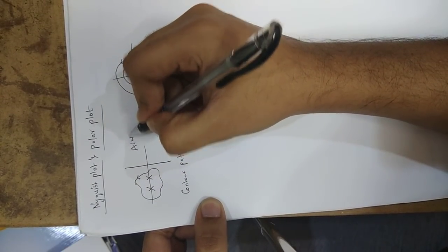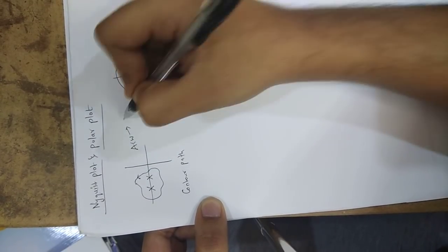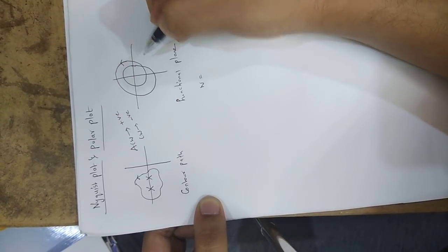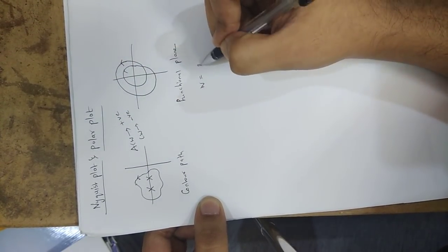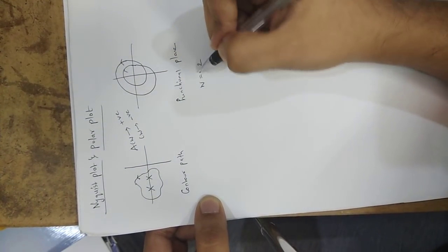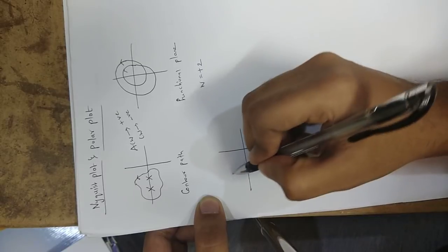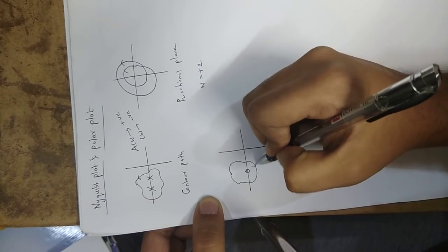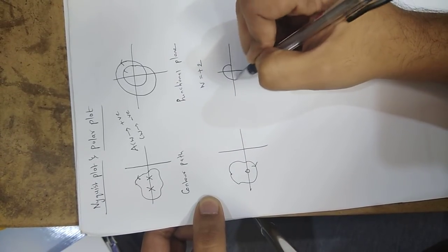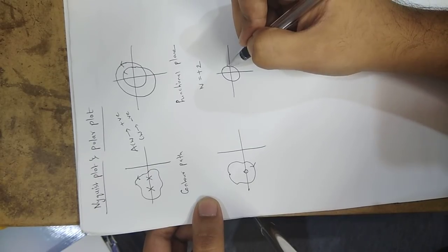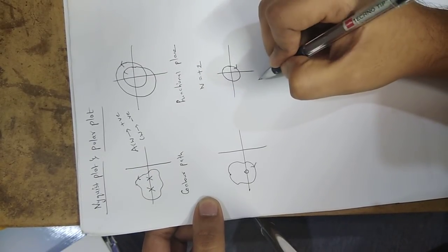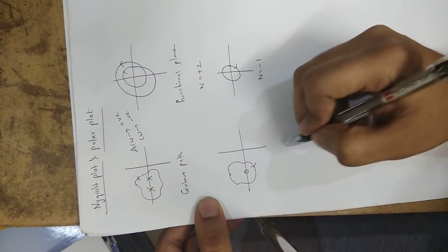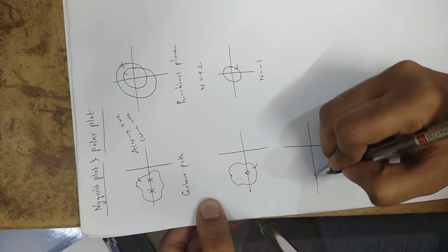So for anti-clockwise direction we'll give n value positive. For clockwise direction we give n value negative. So here in this case there are two encirclements, so n value is 2 and the direction is anti-clockwise, the sign is +2. Similarly, if there is 1 pole and the given direction is clockwise direction, in the functional plane we will get one encirclement with given direction clockwise, so n value will be 1 for one encirclement, clockwise direction for minus.